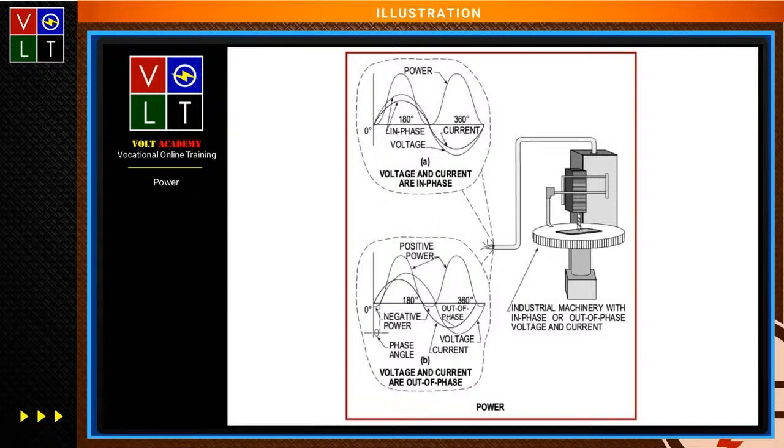So when I look at this, you have a circuit where the voltage and current are in phase, and I look at the power here. This power is going to be equal to the product of the current and the voltage. If the current and voltage are out of phase, then the product of the voltage and current is designated as volt amps at that point, and not watts. That's what I wanted to explain to you when you're looking at the difference between watts and volt amps.